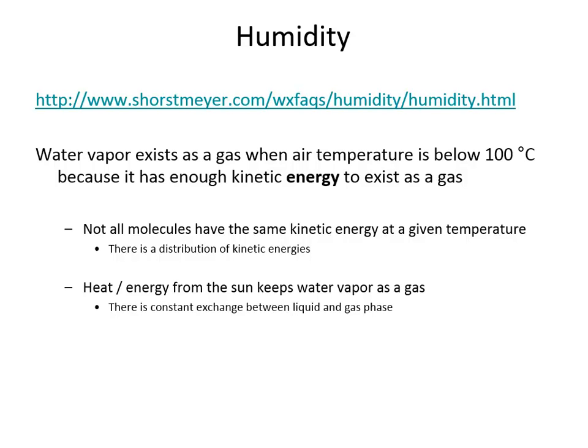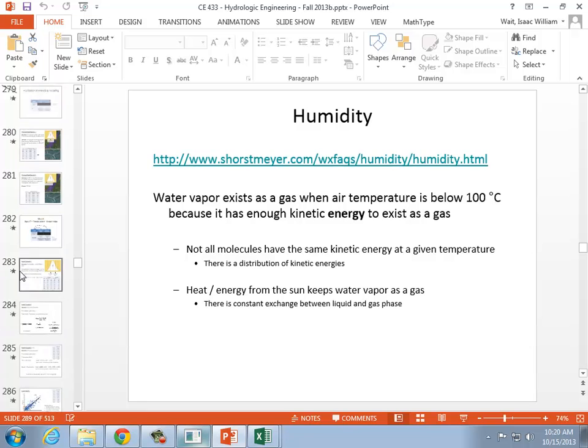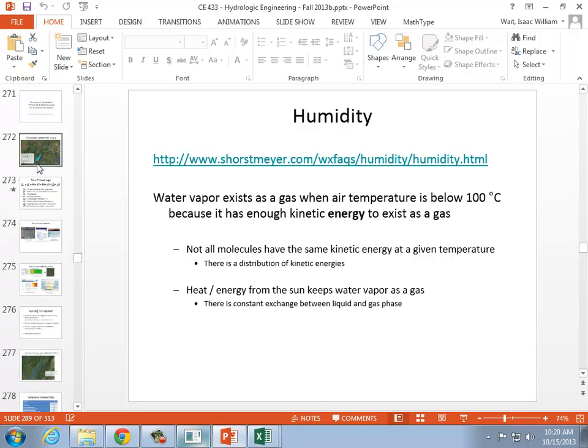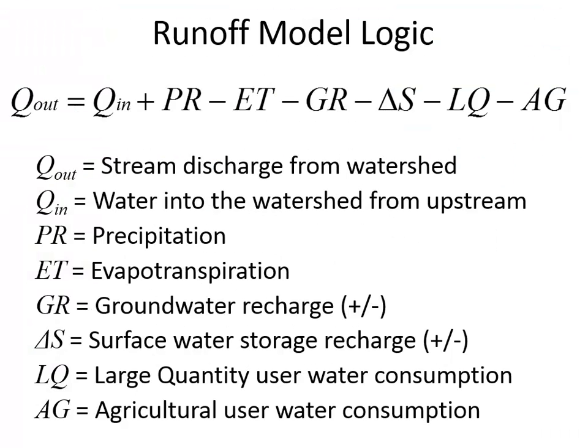Problem 7.1a is just like a watershed mass balance, not really calculating evapotranspiration separately, but more having to deal with the general model of watershed balance that I showed you here. There's a separate runoff model that's presented in that problem, and they tell you how much precipitation there is, they tell you how much a lake level increased, and they give you all the other parameters, and then you need to calculate how much evapotranspiration there was.